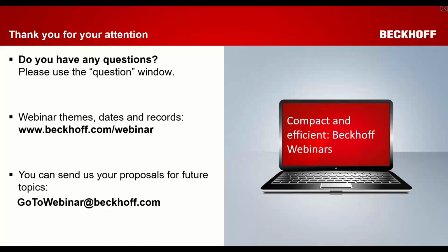But you can, of course, also add the library project as an existing item and choose whether you would like to keep it at the original position, or copy or move the content to your TwinCAT project. Maybe talking about the workflow, from our point of view, if you start a new library development, you should use the reference library feature.